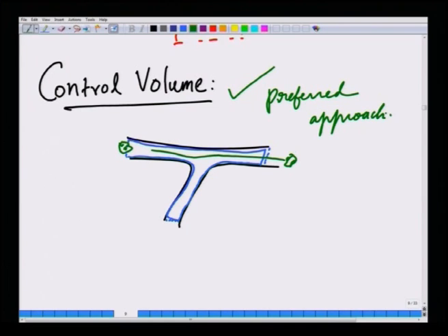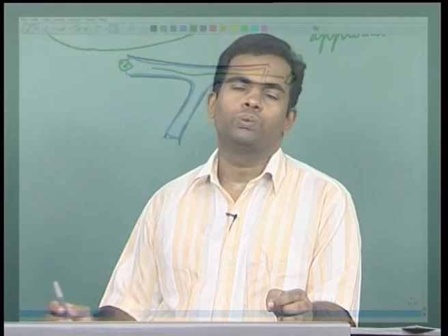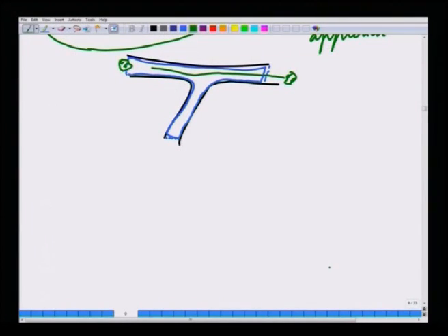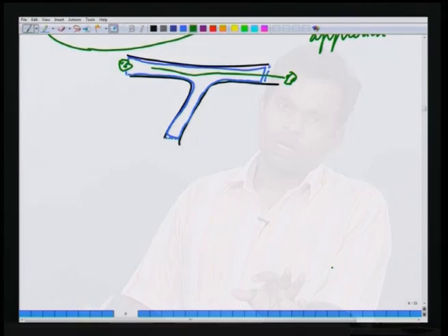Once we choose this approach, then again we land up with the same issue. For example, when we did Eulerian versus Lagrangian description, we realized that even if you want to work only with Eulerian description, we cannot compute accelerations by just taking partial derivatives, because accelerations correspond to an identifiable piece of matter, a point with a fixed identity, and the rate of change of its velocity, not merely the rate of change of velocity with time when expressed in Eulerian coordinates.